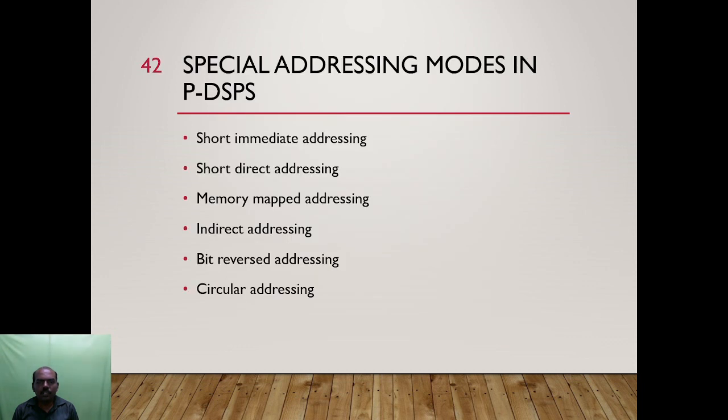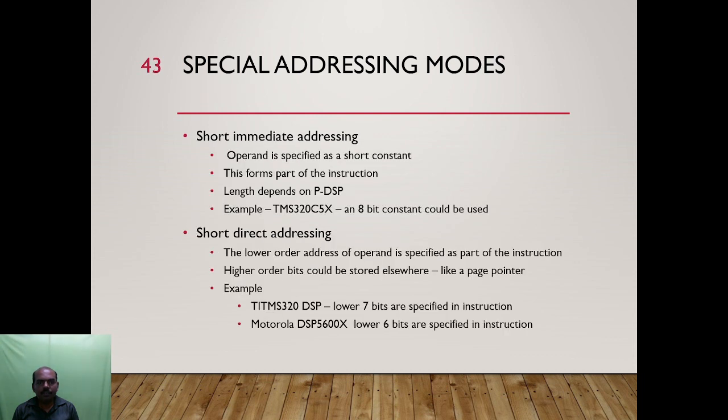Special addressing modes in programmable digital signal processor: short immediate addressing, short direct addressing, memory mapped addressing, indirect addressing, bit reversed addressing, circular addressing. Special addressing mode, short immediate addressing. Operand is specified as a short constant. This forms part of the instruction. Length depends on the programmable digital signal processor. Example: TMS320C5X series, an 8-bit constant could be used.